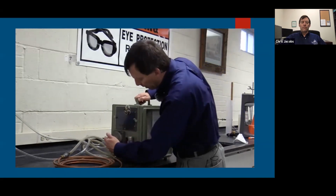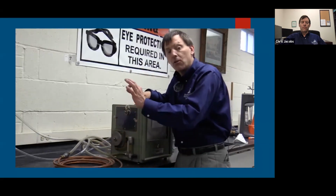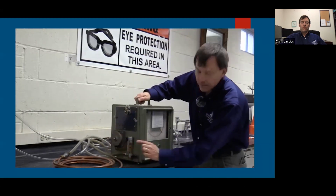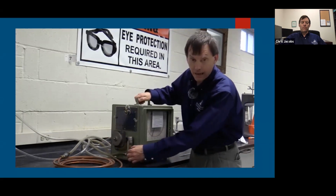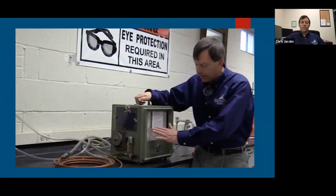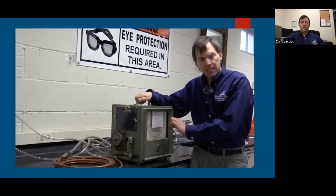Okay, so now I'm ready to actually measure the specific gravity of the gas. I will turn this selector valve to LG, which means low gas, or specific gravity less than 1. And you'll notice that the flow meter went up to about the specific gravity of what I thought the gas was going to be. Now the needle moves down the scale here until it gets to whatever the specific gravity is.